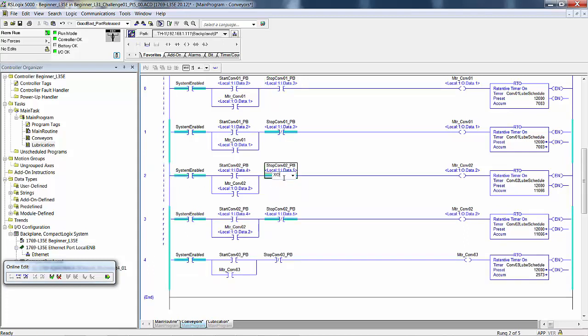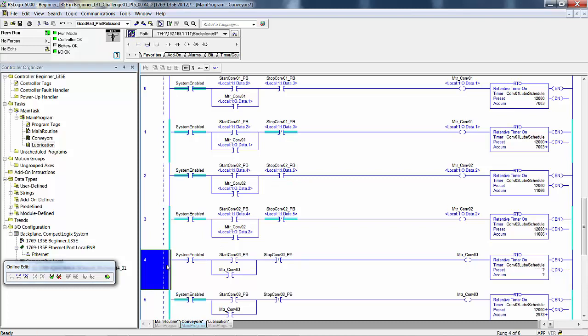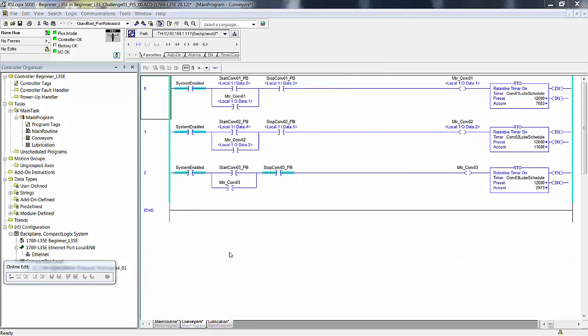Edit mode. And this one I'm going to change back because the logic isn't going to work correctly, because remember we have specialized logic. That is why I was using normally open here, and then I would just turn on input 3 and 5 to simulate stop buttons that were normally closed.